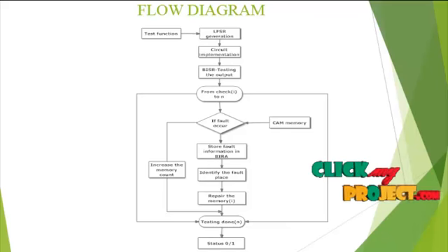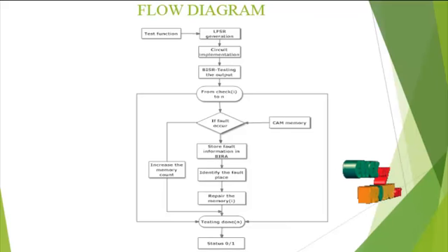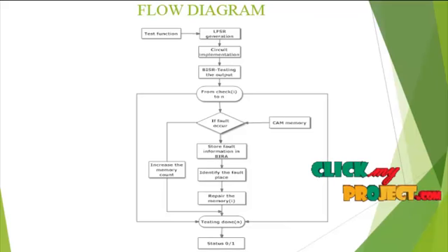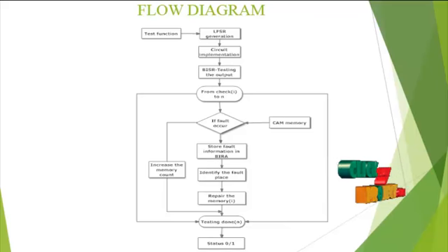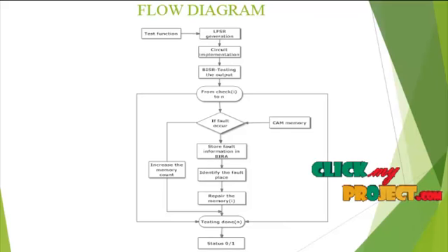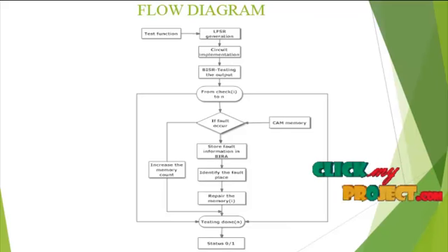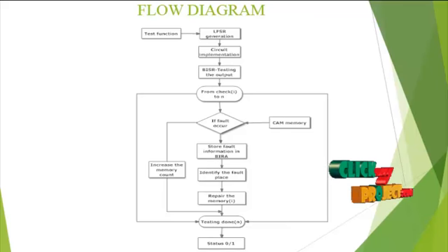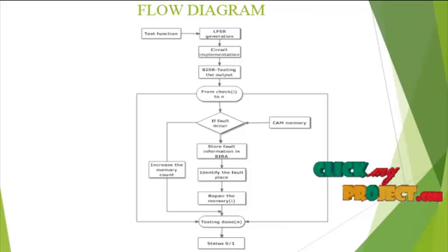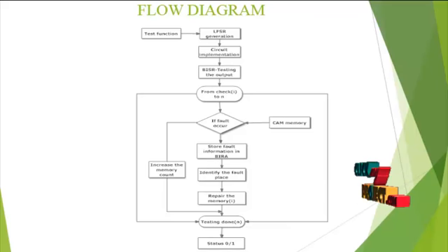In this flow diagram, the BIST unit and the BARA unit are the important factors. The BIST detects if there is any error in the memories. The BARA unit searches for the redundancy memory cells and repairs the faulty cells. When a fault is detected by BIST, the fault information is sent to BARA through the port fault_info.